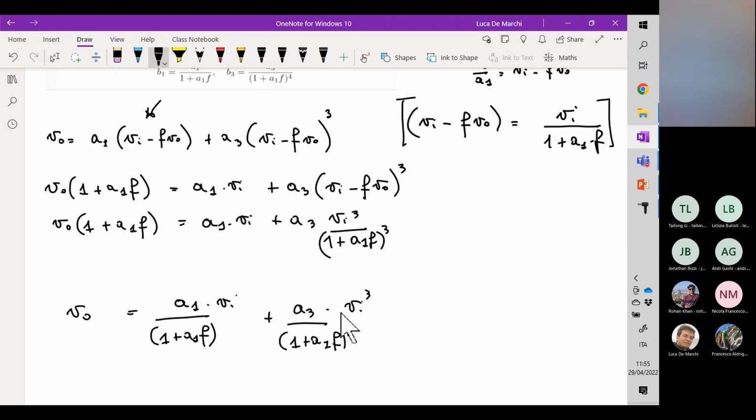And at the same time, 60 degrees implies no oscillation at all. Okay, so of course we need a phase margin larger than 0 to achieve stability, but we must take into account also the fact that in some cases we may want much larger phase margin to get no oscillations in the circuit behavior.